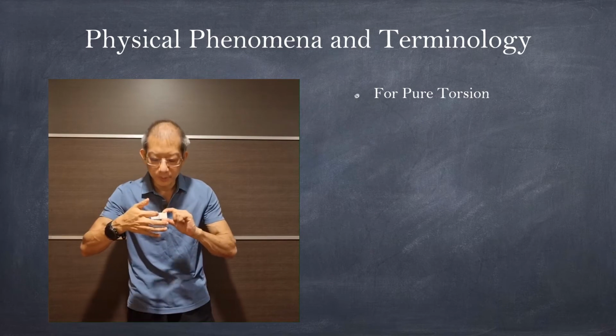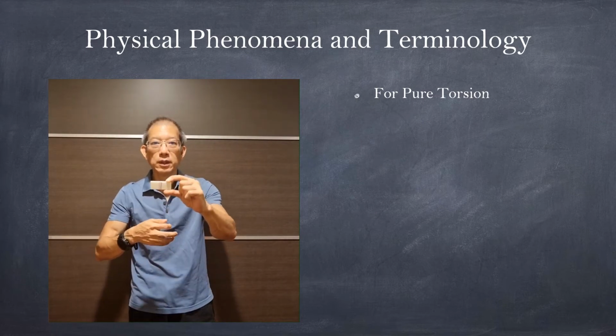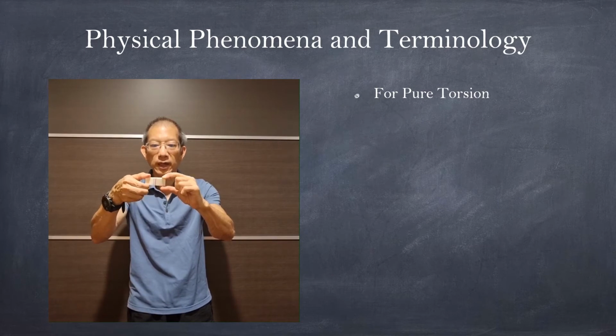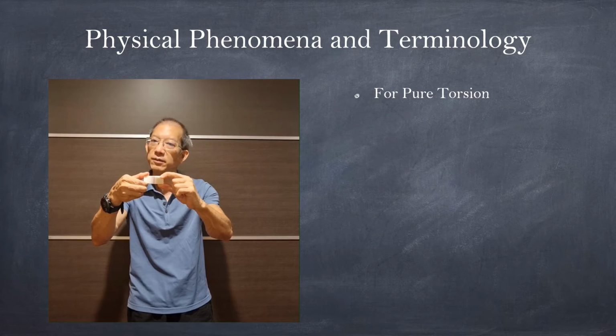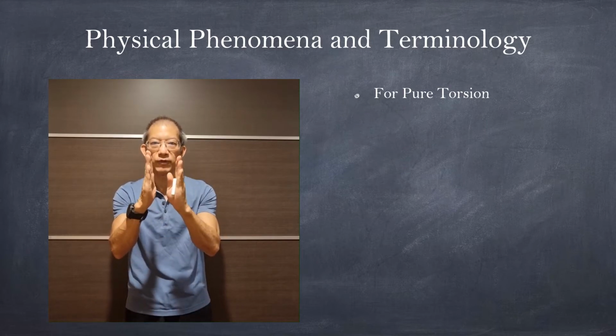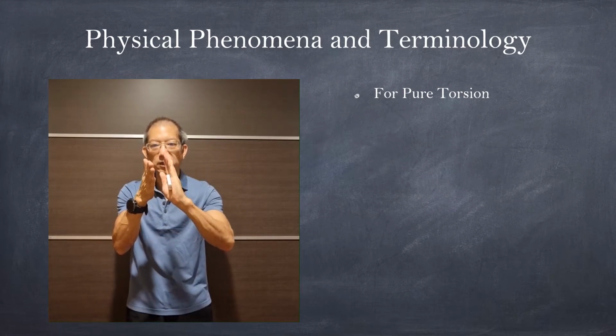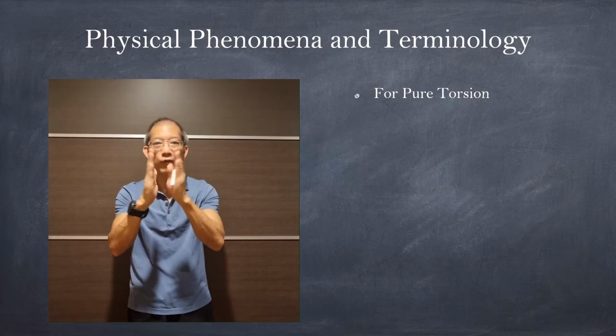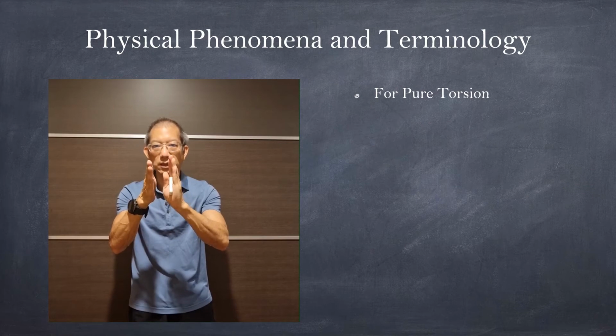So if you look at the two lines here, as usual, it designates the two cross-sectional areas. If I do it like that, notice that the rubber here is twisting. It doesn't bend, it doesn't extend, it's just twisted, right? Now, if you look at the cross-section behavior, it doesn't move away or into each other, it doesn't slide up or down, front or back, no, it's just rotating, right?